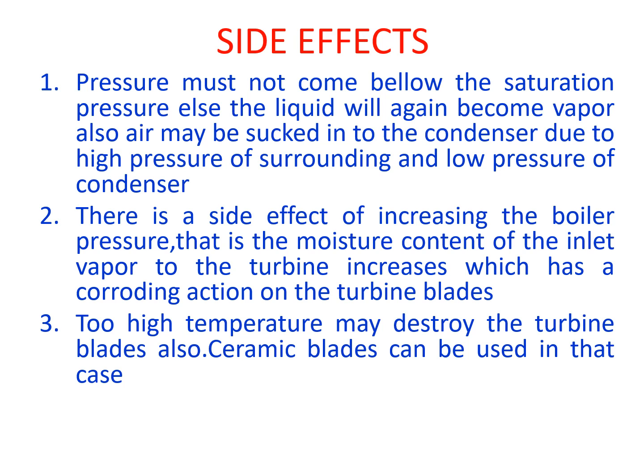So it will not be good for condenser construction. And corrosion will happen if you increase the boiler pressure, since moisture content will be there in the vapor. So we should not increase it beyond a certain limit.